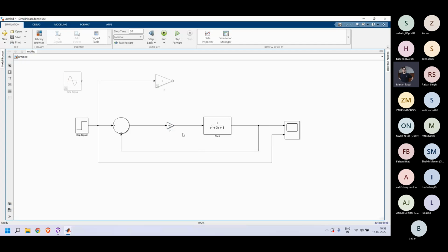The work of a robotics engineer might be in these two areas, to develop a controller, and for developing a controller we sometimes do need a model of a plant. If you want to tune the parameters of this controller, say a PID controller, I should have some decent approximation of how my plant looks.